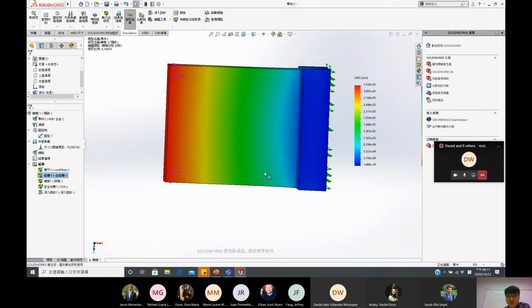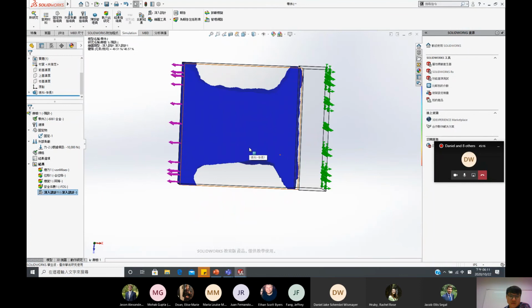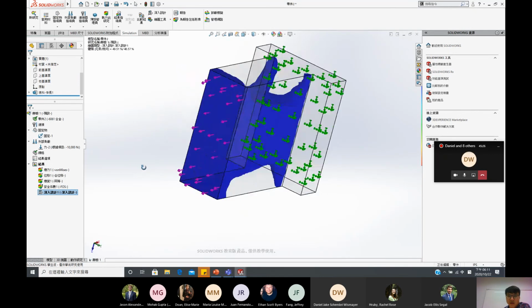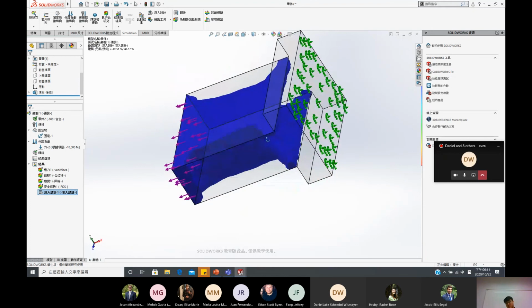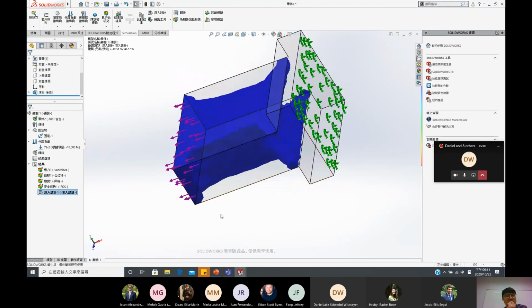As you can see from my mouse moving, this is the region where the applied force is much less intense. So they consider taking this out so you can save a little bit and make it lighter. When you design, you can crop this out if you're considering it, but over here it's not possible because you're applying force at this region, right? So that's why it's not able to do that. This is also one of the considerations you should keep in mind.